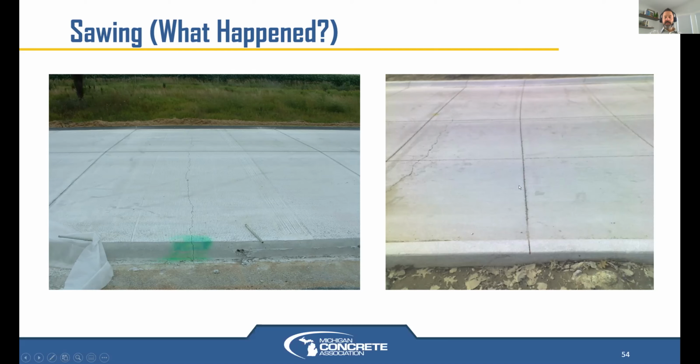So in both of these cases, what could have helped would be, at the very least, some plastic to cover it up to hold a little bit of heat in, blankets if it's really cold below freezing, changing the mix design slightly if possible, if allowed by spec or by mix design, to reduce some supplementary cementitious materials, using hot water instead of the standard cold water, well water, or municipal water supply.